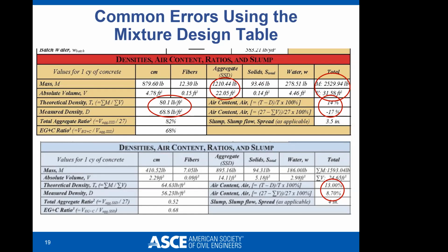And same thing here on the last one. You'll see that they have two different air contents. Now, if you come up with the calculation, and in one case it comes out to 12.9, in the other case it comes out to 13.1, you're probably correct. It's just a matter of significant figures or rounding from that standpoint. But when you're off by several percentage points, you should have an issue.